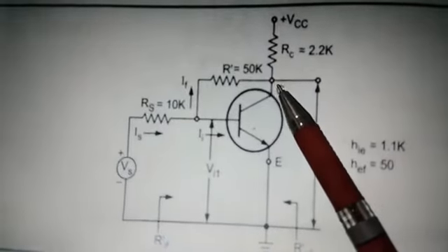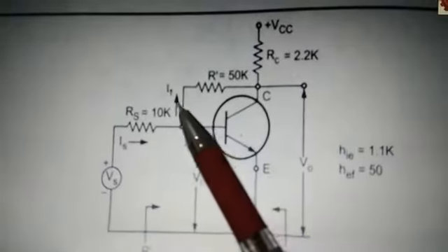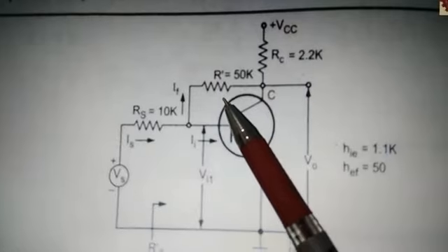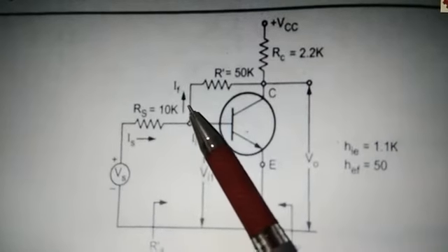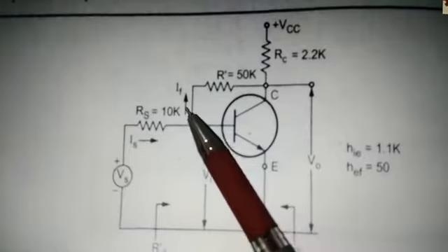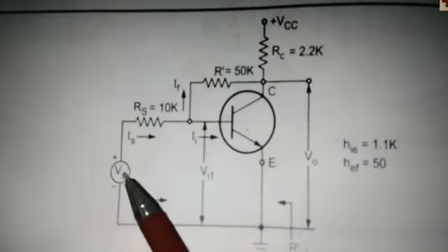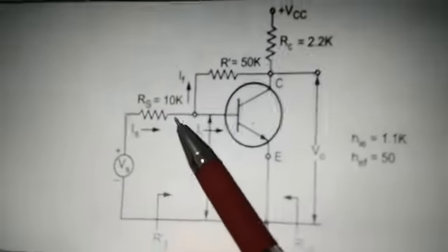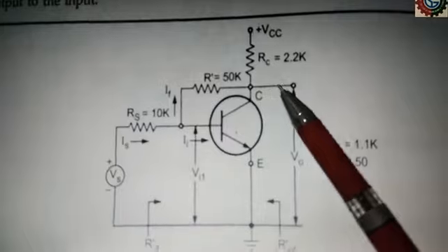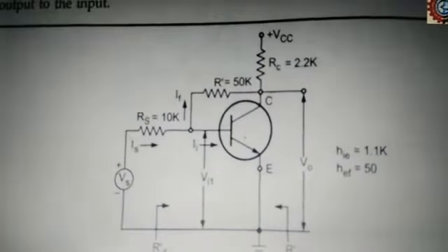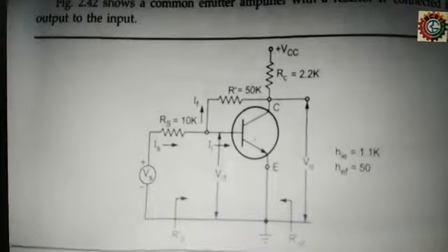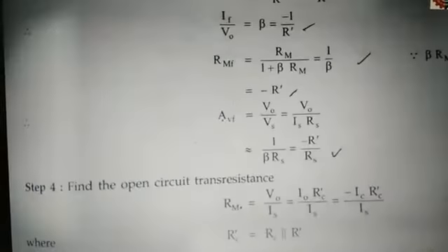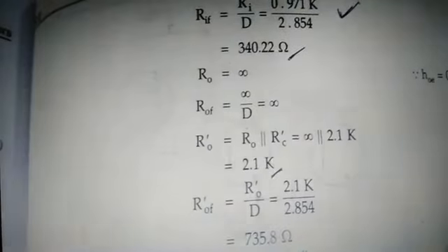Here the output is voltage and the input is the feedback. The output voltage is the input to this feedback circuit, and this is the output current of the feedback circuit, which is in parallel with this Norton equivalent of this source Vs and Rs. That is a shunt circuit, and hence it is voltage shunt feedback, and we calculated a number of parameters of this circuit. Now let us go for the second example.